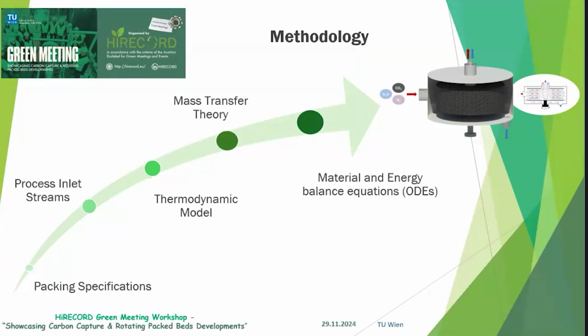It is essential to choose the appropriate thermodynamic model with the occurring enthalpies of reactions of reactive absorption or desorption. We have equilibrium pressures with respect to loading and temperature, which is vital in order to have an accurate model for this type of process.